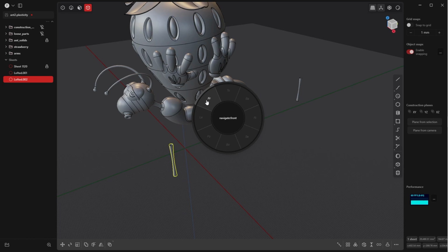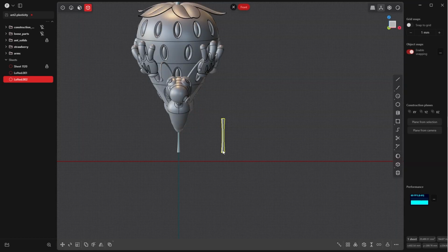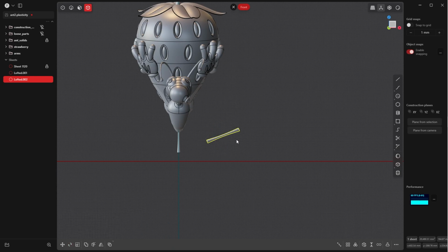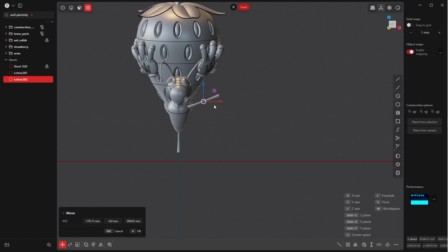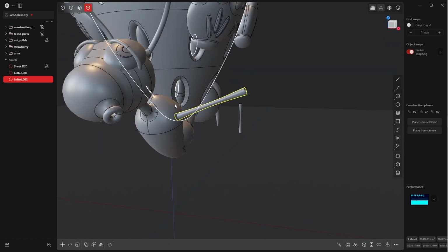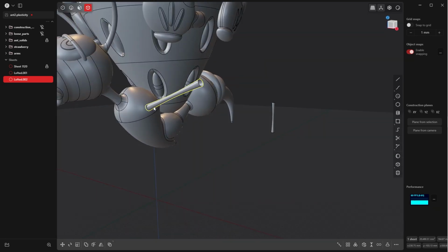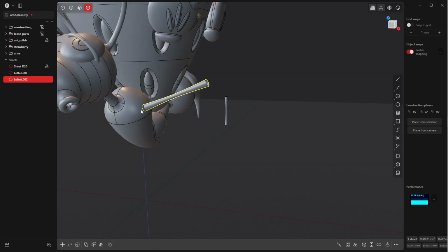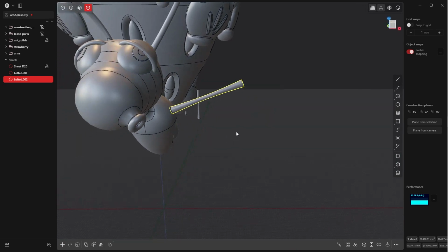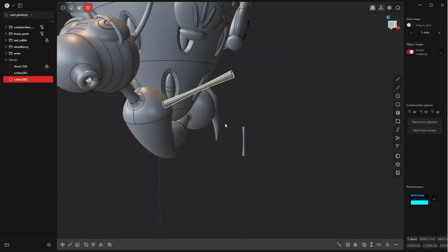This will be our first limb. So let's see how we can do it. So there has to be an upper arm and a lower arm, obviously. Let's start by pressing double R, and you know the drill, you know these basic commands. First thing we want to do is find the correct location of the start of the arm. Find the location of the shoulder, and always check your model from all perspectives. Don't work in only one perspective.